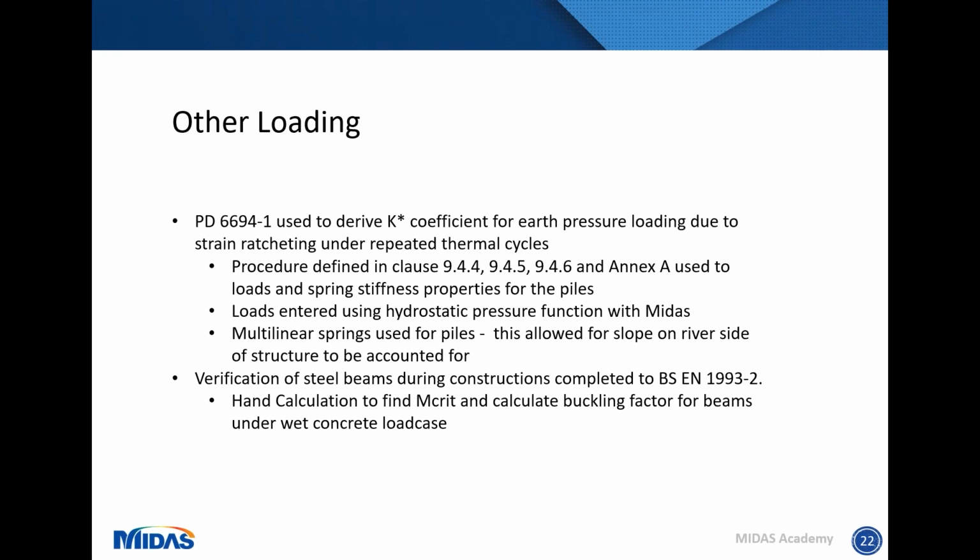The verification of the steel beams during construction was completed to BS 5950-1 1993 Part 2, but was done as a hand calculation to find the critical moment and then calculate the buckling factor for the beams under the wet concrete load case. I'm aware within Midas, again, there's an option to create a 3D model where you might define the beams as plate elements, and through that be able to find your critical buckling factor under eigenvalue analysis.